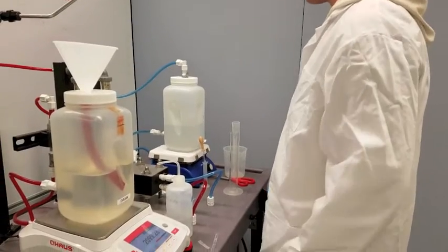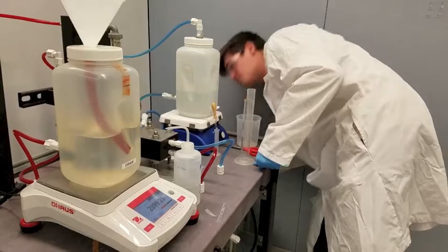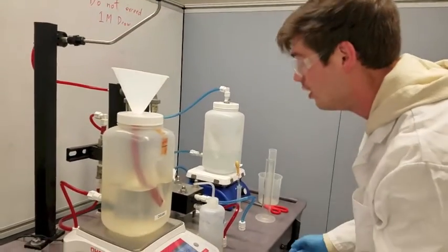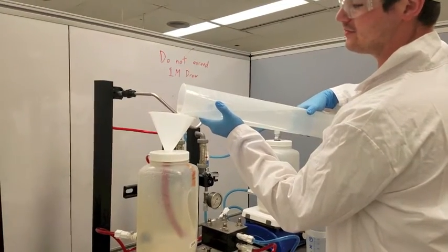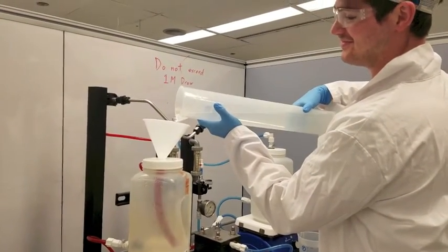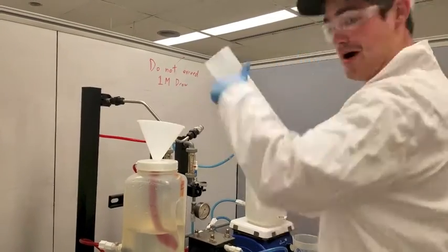In order to begin performing forward osmosis, a few steps must first be taken in order to set up the experiment. First, begin by turning on the chiller to the desired temperature, and then filling the feed and draw tanks with 2 liters of distilled water each. Next, add a stir bar to the feed solution to facilitate mixing and turn on the mixing apparatus.